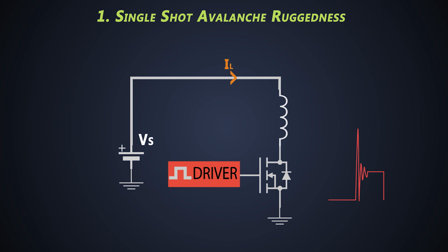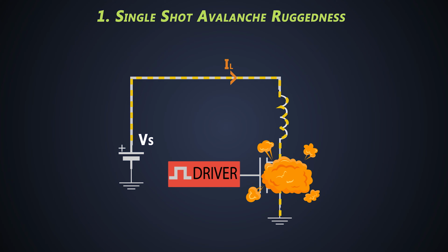When the energy and current generated by this event are low, the impact on the MOSFET is very negligible. It can sustain that and discharge the inductor easily. However, if the inductor value is high, due to that there is high induced flyback voltage, and because of that the avalanche induces either high energies or high currents in the MOSFET. Then it can be destroyed.